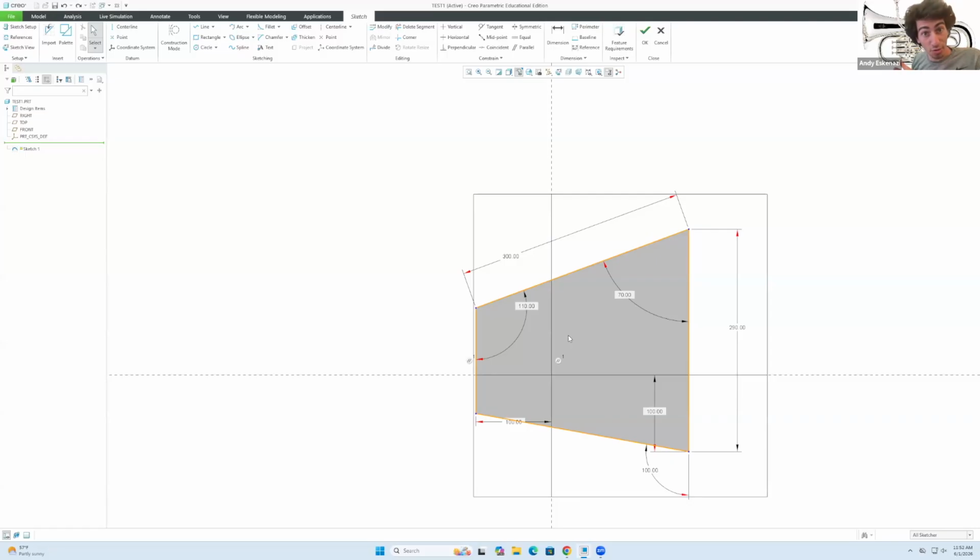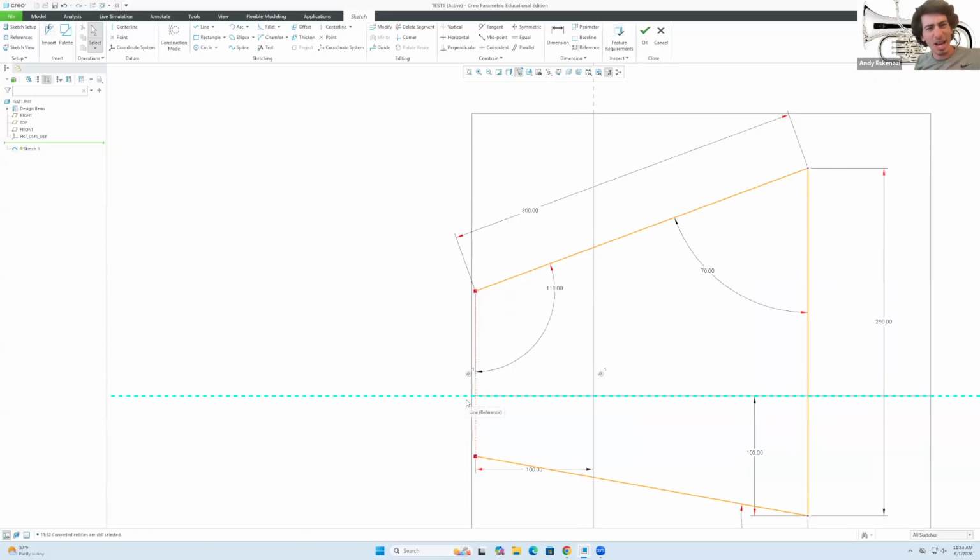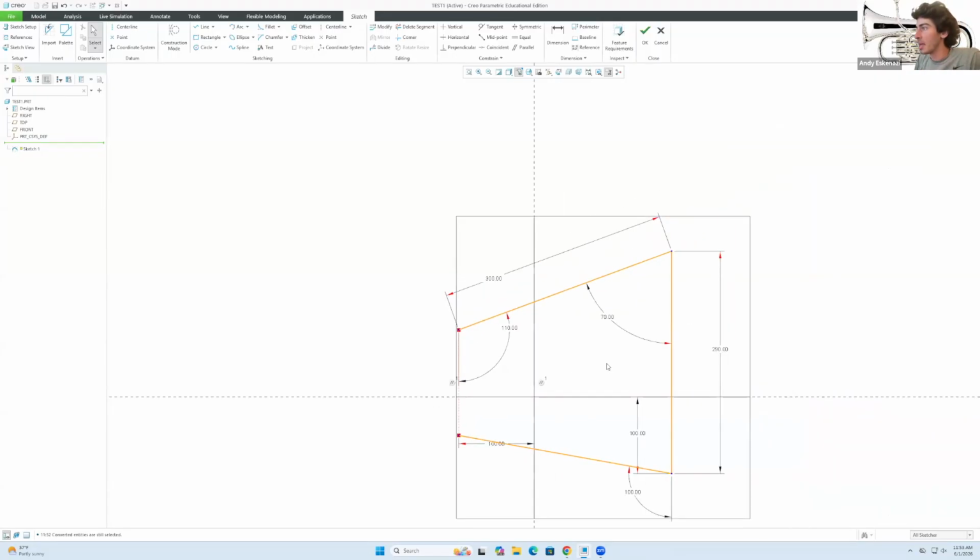Another thing you could realize is that if I right click on that line and then left click, you see that this panel appears, which is what we saw earlier. The most relevant thing from here is that little button called construction. What does construction do? You click in there, and essentially it grabbed that line and made it transparent. The line still exists, and for dimensional purposes it's very useful because it's a reference line, a construction line. But this is no longer shaded because in the face of the sketch, it's as if it was never there.